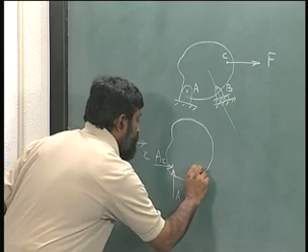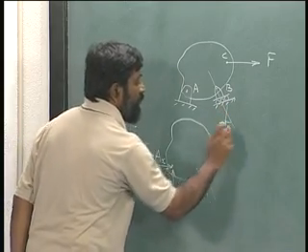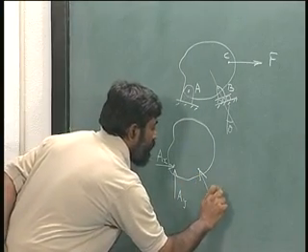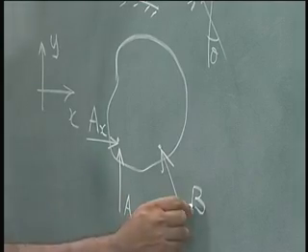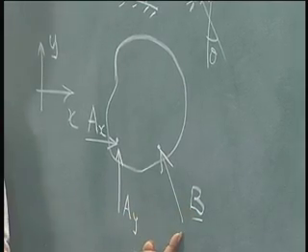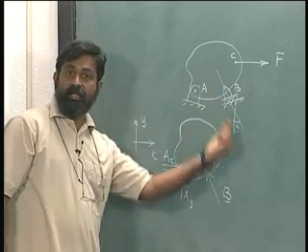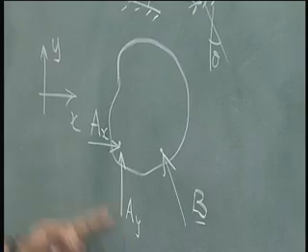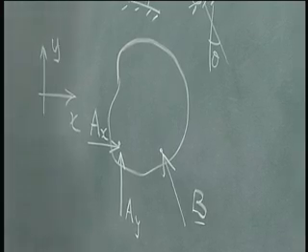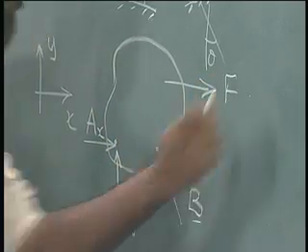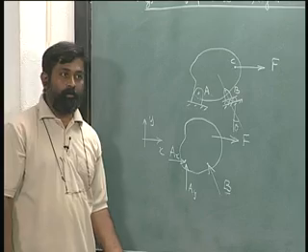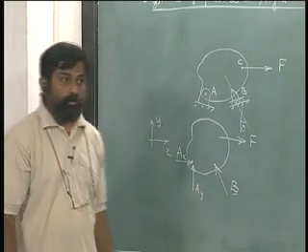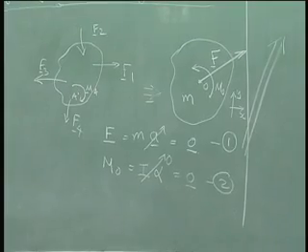And there is a particular direction to this, so let me just represent the direction. Let us say this angle is theta with respect to vertical, so I can represent this as the force B. Mind you, in this particular case I know at what angle the force is acting, which means only the magnitude is unknown. Here the two unknowns are Ax and Ay. So if I complete it, this shows the free body diagram. This free body diagram is essential in order to solve for the unknowns using systems of equations. So let us write it down.